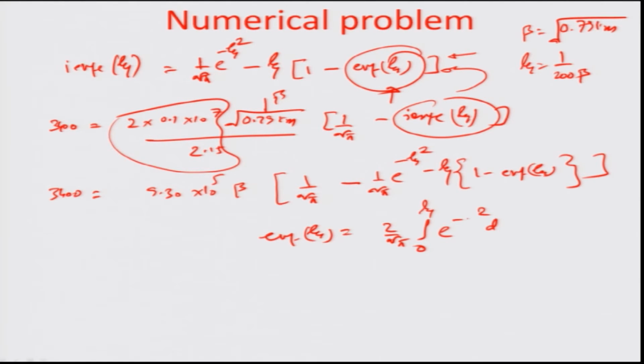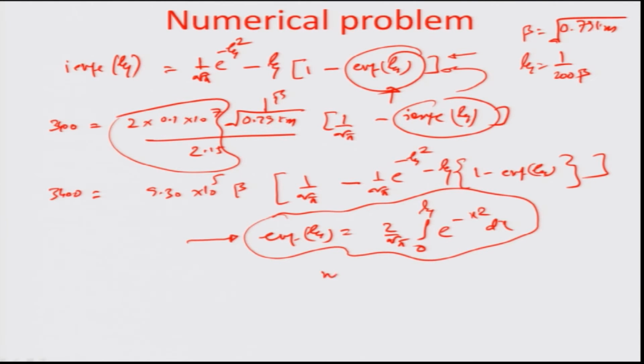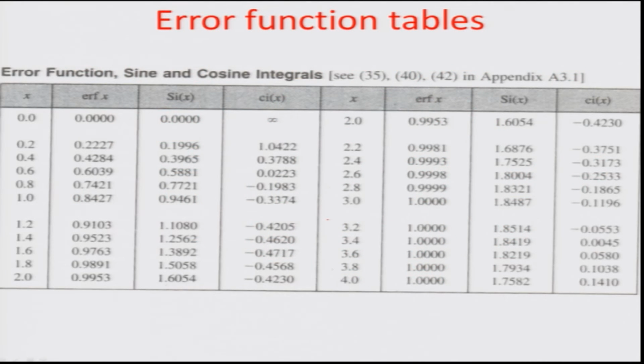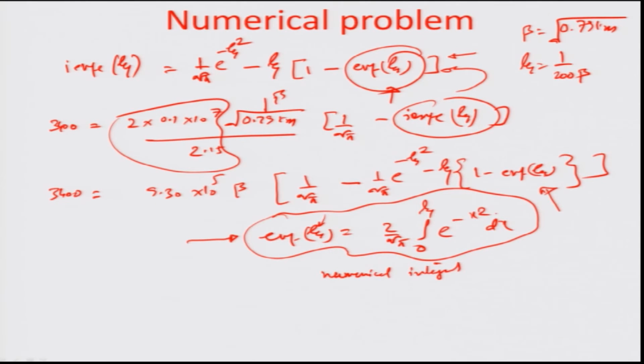So, as I already had mentioned, the error function is a numerical integral and there are values which are arrived at as approximation corresponding to the various values of zeta; you will have different values of the error function. So, the standard tables look at what is going to be the error function for a given x parameter. So, x is zeta in our case, and we have to iterate from here to find that zeta value corresponding to which, if we outlay the value of the error function in our solution right here, we already know the value of zeta from which this thing would happen.